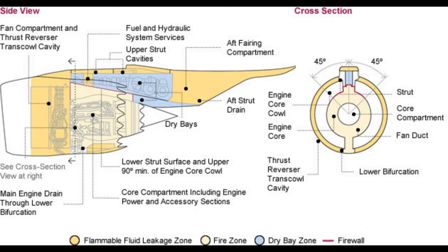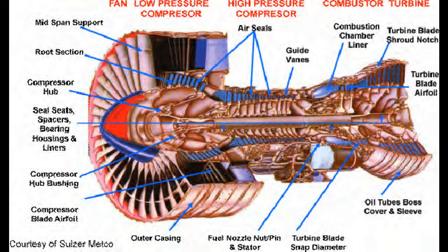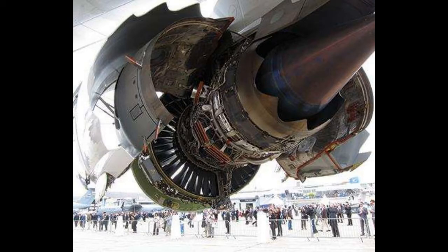Turbine engine fire zones. A fire zone in a turbine engine installation is any area in which an ignition source together with combustibles, combustible fluid line leakage, or combustible mixtures may exist. So when we're passing any kind of flammable fluid through a turbine engine zone, that is going to be a fire zone. The power section, combustor turbine and tailpipe sections, which contain lines and components carrying flammable fluids, the engine compressor and accessory section, and any complete power plant compartment in which no isolation is provided between the engine power section and the engine accessory section. Obviously, we're going to have flammable fluids passing through those areas.